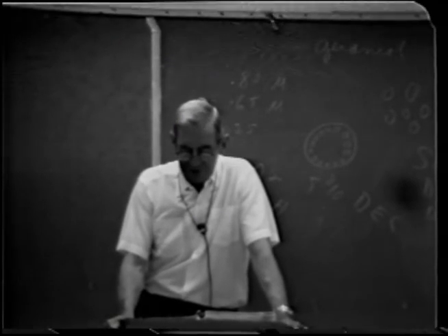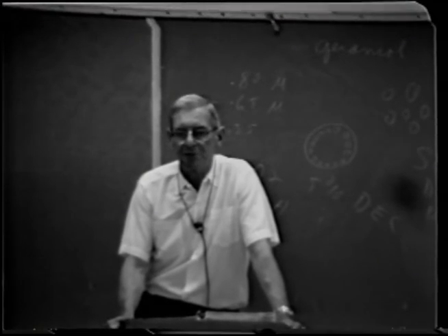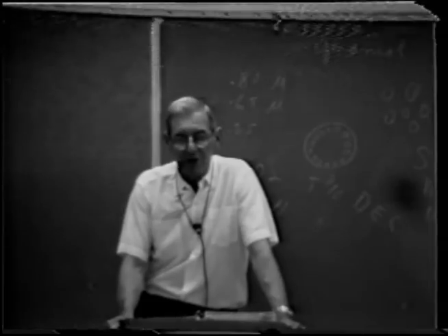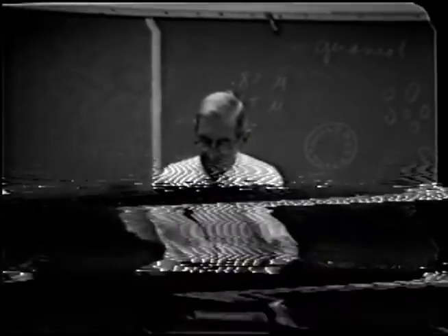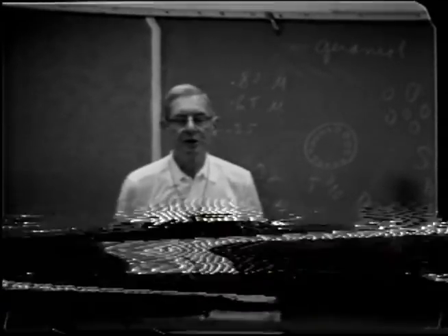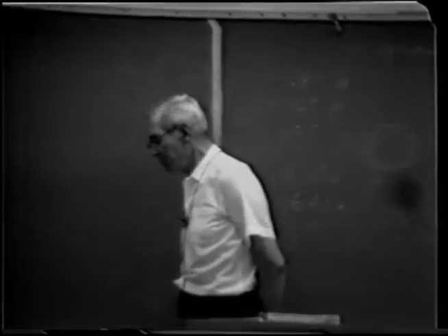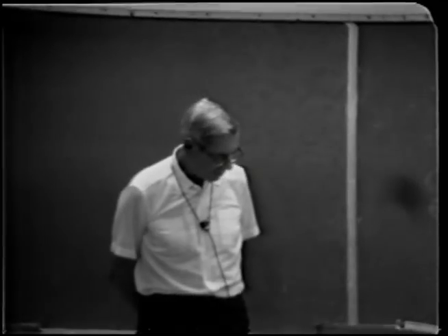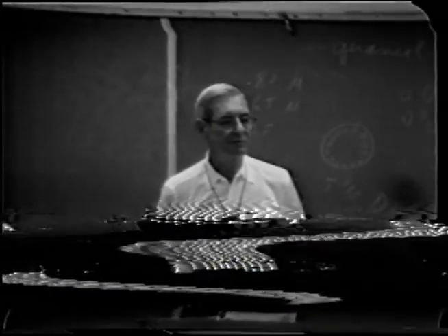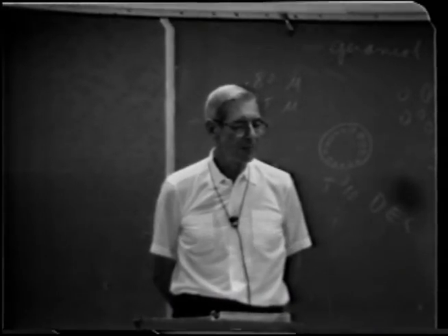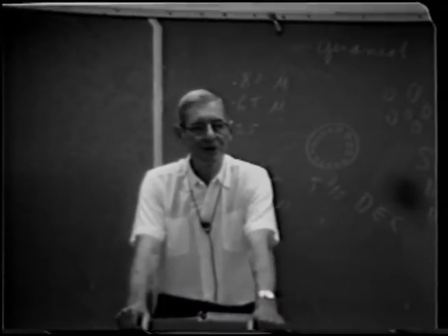Well, now I want to go on to fillers. There are formerly three main types of fillers. Recently another type has been added to it. The former three main types of fillers were siphon, vacuum, and gravity. And recently, I say recently, within the last several years, the pressure fillers have become more widely used, especially with the advent of slightly carbonated wines, those having just 7 pounds carbonation, I should say.